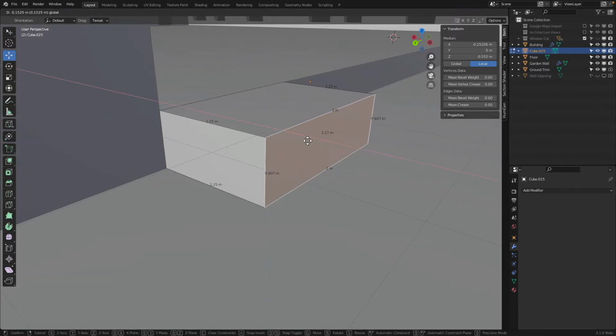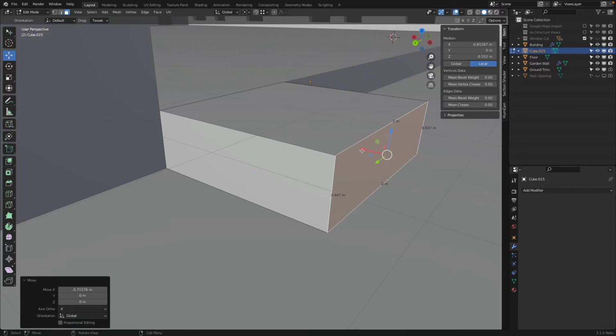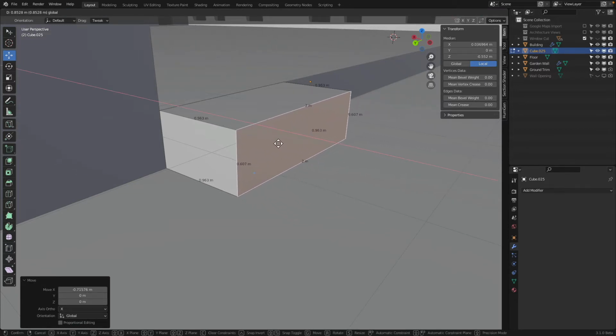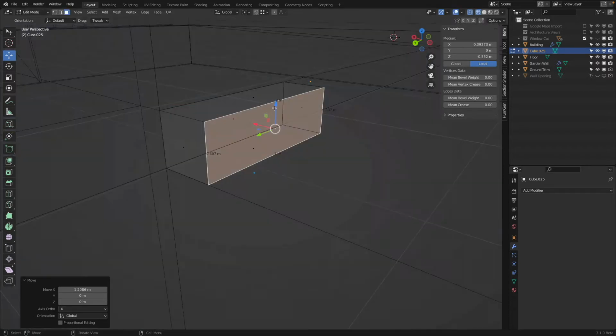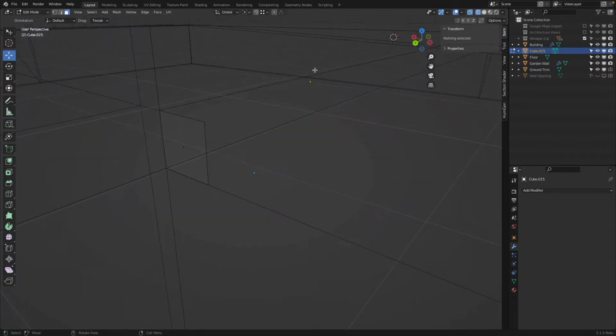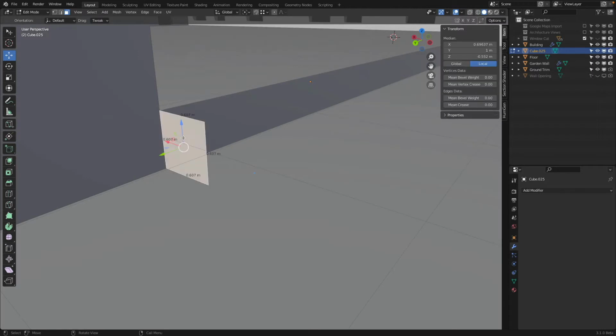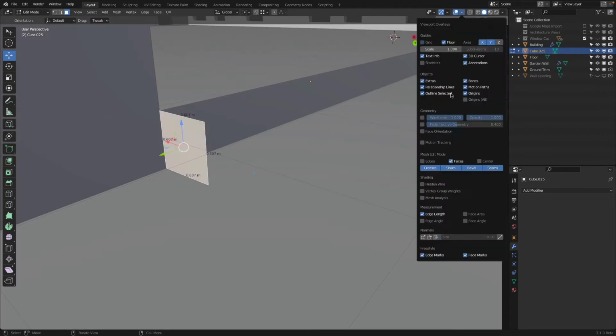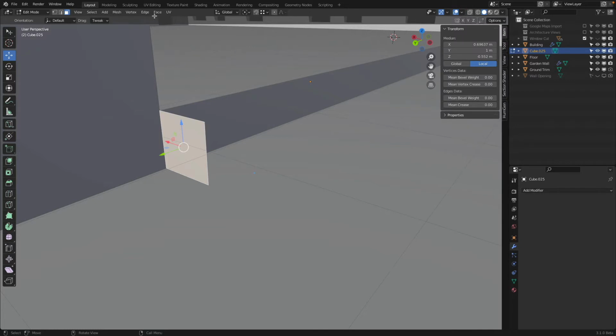And because when I move this one face, the other edge adjusts, you can see that I get an instant readout. Now I can move this a little bit, hold shift, and then it goes slower, and 0.607. There we are. Beautiful. This edge, face, we delete. This face, here we can turn this off. We subdivide. Then this face I delete.